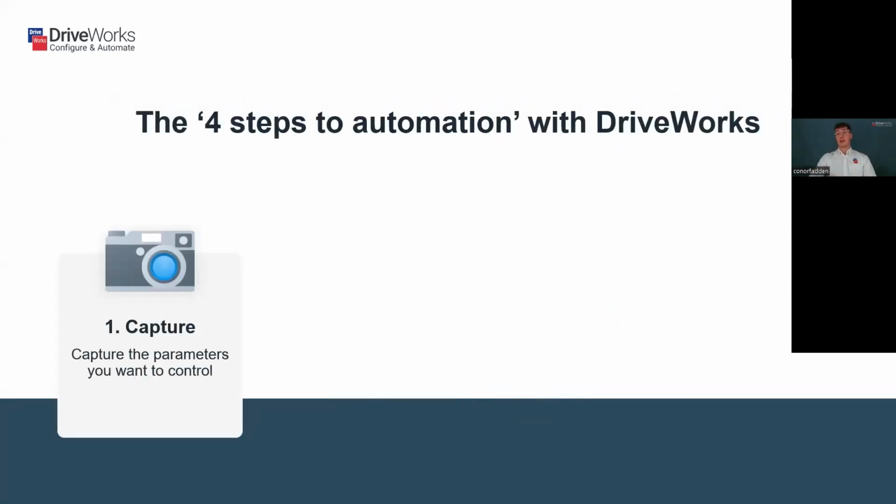So I hope at this stage you're all thinking, wow, this sounds amazing, but how do I get started? Well, for those of you who are unaware, there are actually 4 steps to automation with DriveWorks. Now, the first of these is to capture. I feel like I might have covered this a little bit previously, but you want to capture the parameters you want to control. So whether this is the height, the width, the depth of the actual cut that you're going to do in your extrude, what you're actually going to do is capture all of those in DriveWorks.